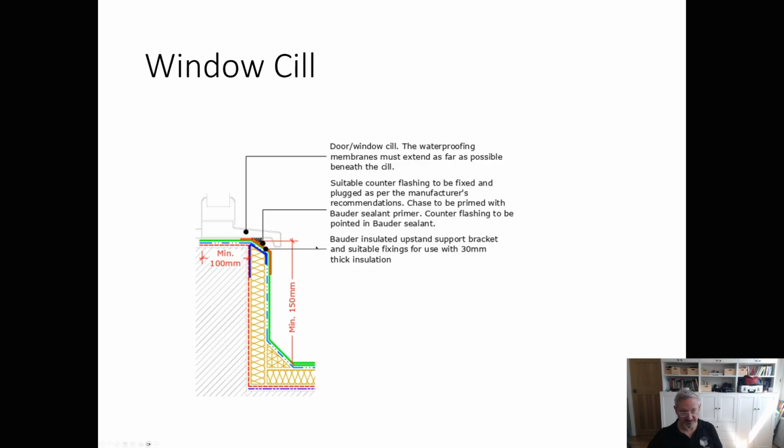And again, under the windowsill, I'm going to angle grind. I'm not replacing the window. The window's relatively recently been replaced, so I'm going to cut under the window there and just stuff some flashing in and try and do this sort of methodology.